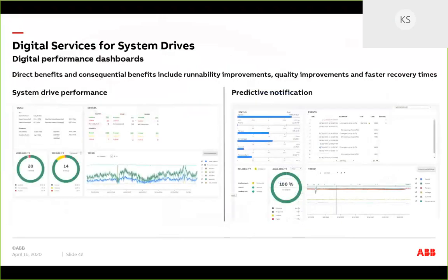that give you insights across your fleet, not just one drive or not just when we're there. It's all the time. I don't expect you to read all these graphs, but those bars all mean things. Over here, this is your torque, your voltage, your current, your temperature. Remember the KPIs that I showed you? You now have those regularly. You can look at your availability and your reliability, and you can look at things that are degrading over time. When Matt was talking about your voltage drifts, you can start picking up problems with the capacitors, the dielectric material. You can start seeing things, and you can know that you're safe, reliable, and optimized.